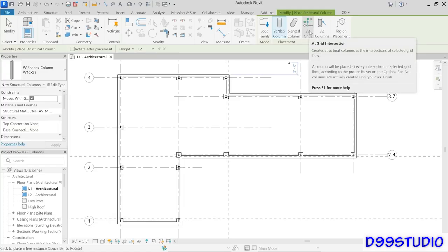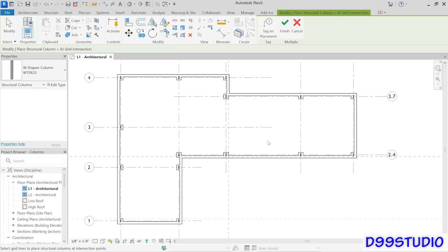So let's choose the at grids option next. Typically, this works best with a crossing selection. So we're going to go right to left this time. I'm going to start in this empty space right here, click and drag to the left until I've highlighted the 4 internal grids only. I'll let go, and it will ghost in a piece of steel in each of those locations.